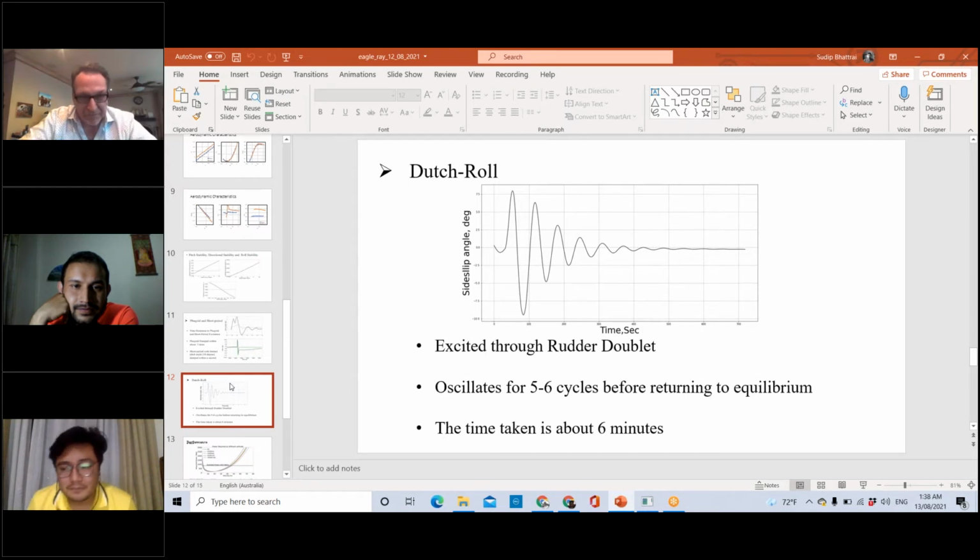Yeah, so with the angle of attack, right? Typically we are at a high angle of attack even when we're cruising. And so when you approach to land, I sort of pitch up to not stall, or to maintain the lift. And I also want to decrease the speed. And so I keep pitching up, but unfortunately the nose landing gear is still so tall that I tend to touch down with nose landing gear first. And so that was one problem that was a bit hard for me to avoid.